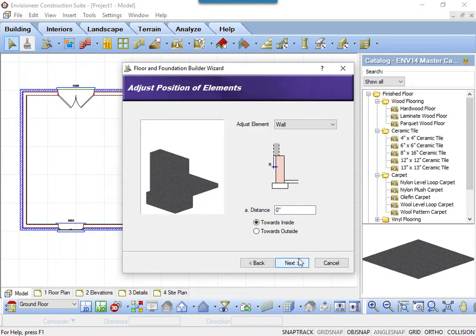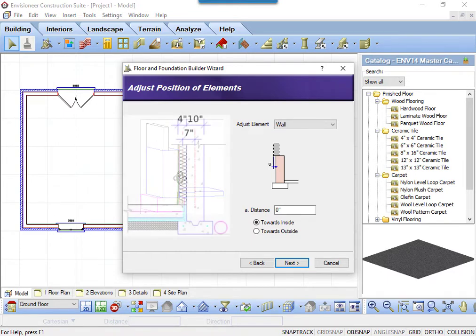For adjusting the position of the basement pieces, there's a diagram to the left. Right-click in the diagram box and select Hidden Line to see a more telling view of the materials and how they relate to each other. The overall thickness of the basement wall is 10 inches for the concrete and 4 inches for the stud and finished materials. The footing automatically centers itself under the core portion of a wall. With just a concrete wall, that would be perfect.